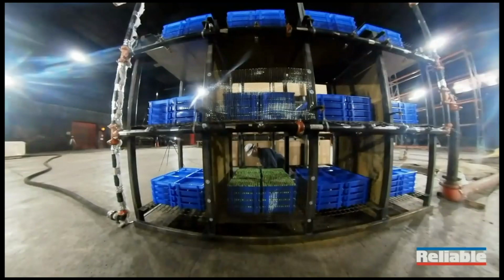We have a video here, and I'm going to tell you what's going to happen because it does have sound and I don't want to shout over it. What we wanted to do was start a fire underneath the batteries and set the batteries into a state of thermal runaway that also became cell-to-cell thermal runaway, meaning a failure of a cell that starts a chain reaction that goes cell to cell. Once that chain reaction occurred, we wanted our sprinklers to operate, and then we wanted to see how they performed. So let's give this a go here.